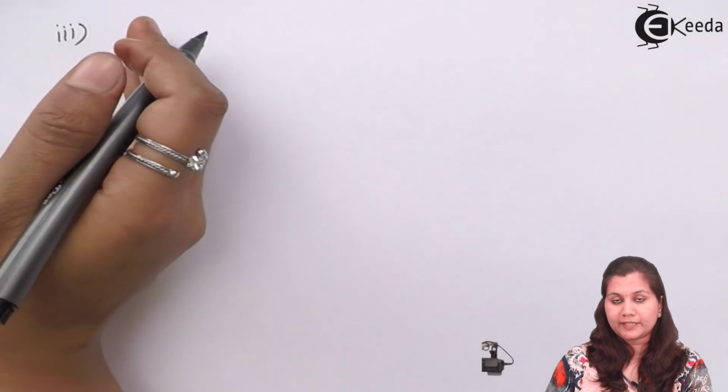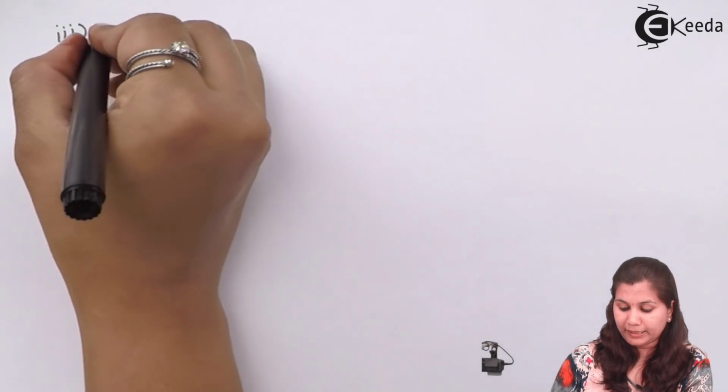Now, in the capacitive transducer, when we studied the advantages, we saw that it has high input impedance. So loading effects are minimized. But the output impedance of the capacitive transducer is also high. But for loading effects, it is required that output impedance should be low. So, due to the high output impedance, there is some loading effect produced in the case of the capacitive transducer.